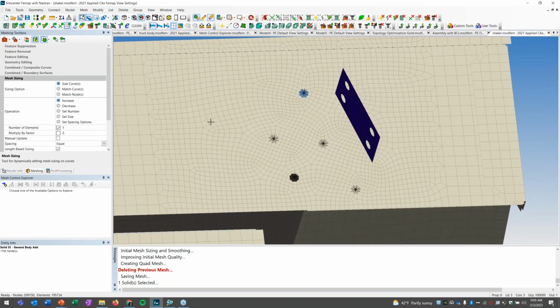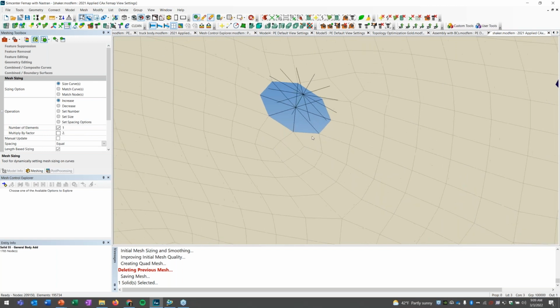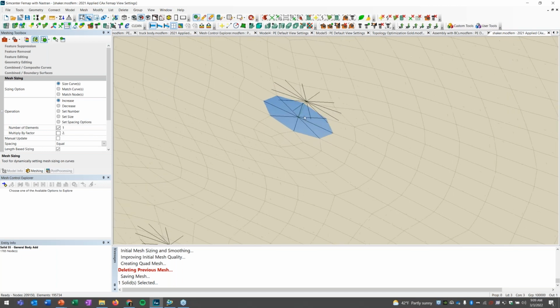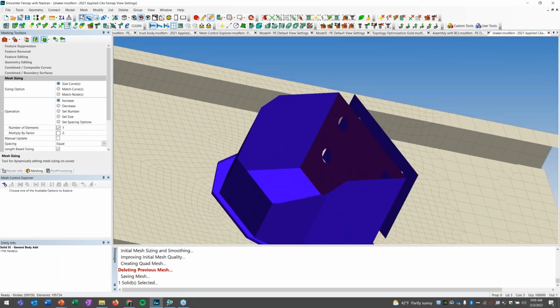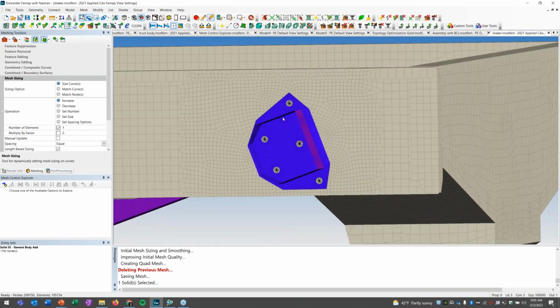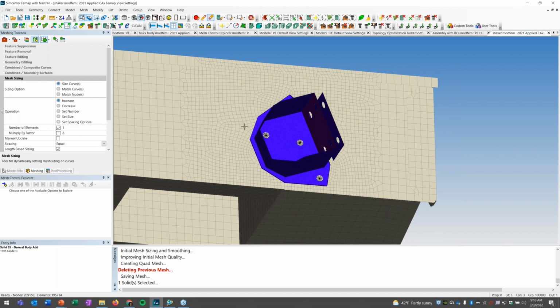It's actually a visually appealing mesh pattern, dominant quads. You'll notice on this inside connection too, where I had this rigid element, since this portion of the structure was defined by the existing mesh, it maintains those nodal locations, and I don't have to worry about rebuilding the rigid element that connects to that region there. So this is a great way to add mesh refinement to portions of your model very quickly, resulting in high quality elements as well. So it's really quite nice there.